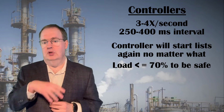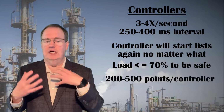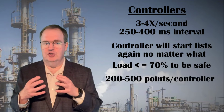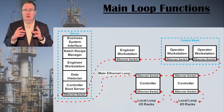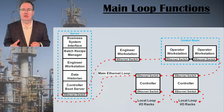Depending on the controller and the complexity of the task to run, 200 to 500 I/O points on a controller is a comfortable loading, which will determine the number of controllers needed for a facility. On the main Ethernet loop, controllers exchange data and messages to each other as needed.